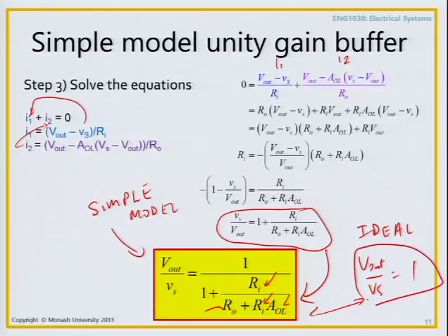And this is not out of the realms of probability because, in fact, these values, depending on the op-amp that you buy, are going to range from close to ideal, which is high input impedance, low output impedance, whatever, to not so close to ideal. And in fact, also, this parameter here, which we assume is very large, actually tends to get smaller and smaller as we use the op-amp in faster and faster electronics. Okay, so